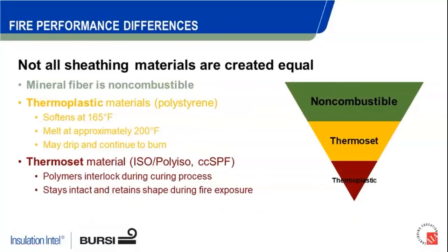And back to my point that not all sheathing is created equal: mineral fiber, of course, being non-combustible, the thermoplastics, the polystyrenes, versus our thermosets. A color issue there, but again, thermosets being the second best in that they have a stronger chemical bond, which holds up better under fire.